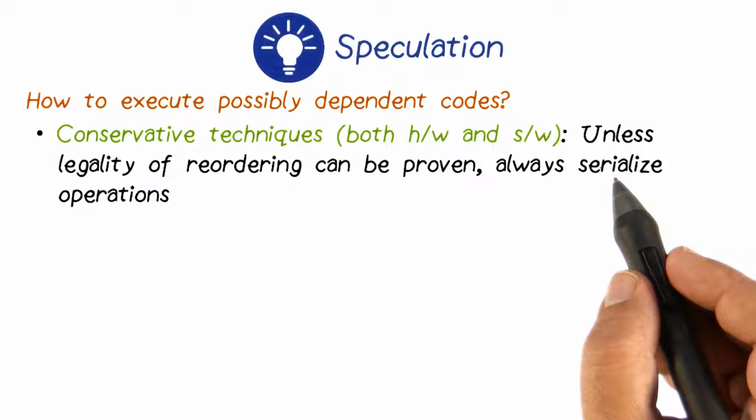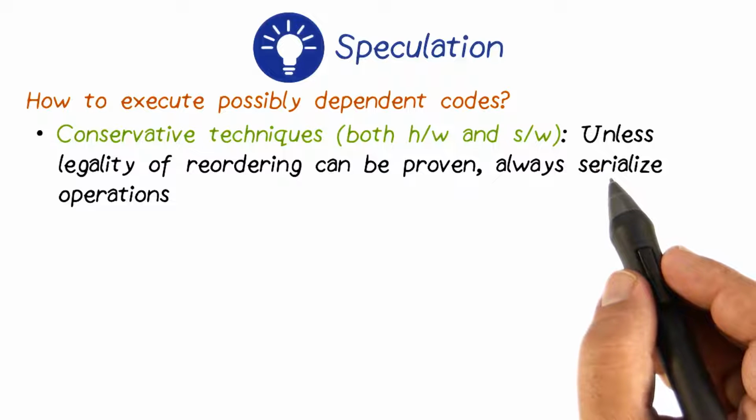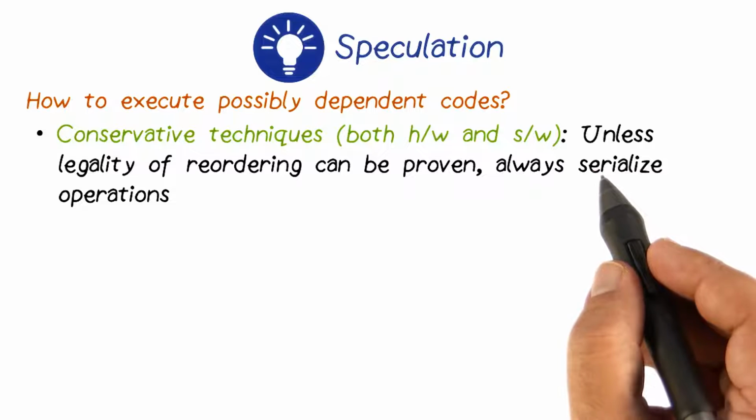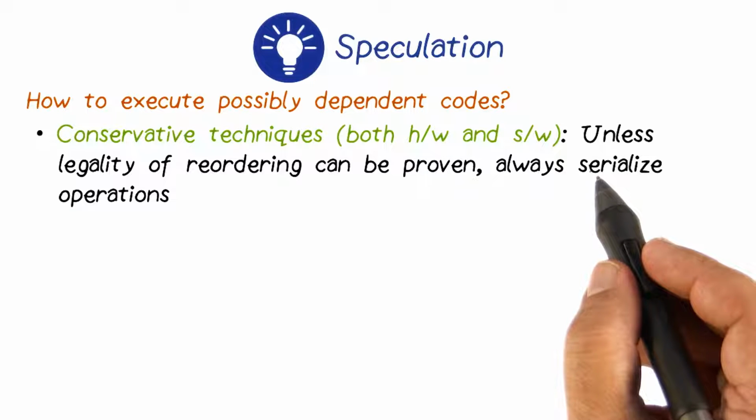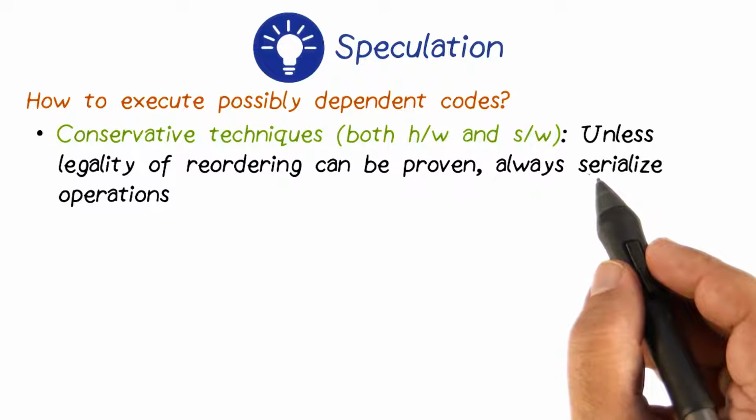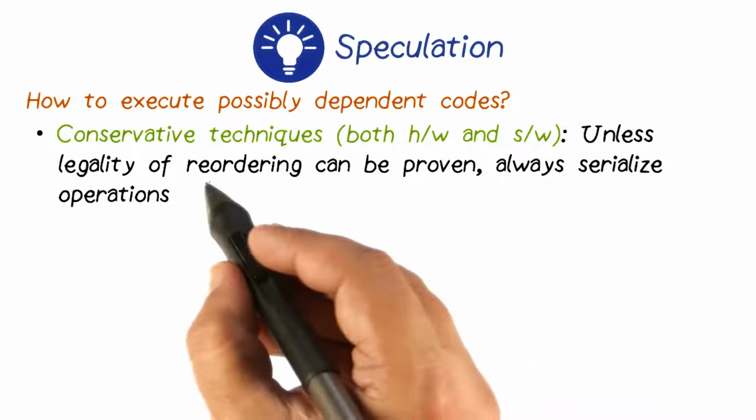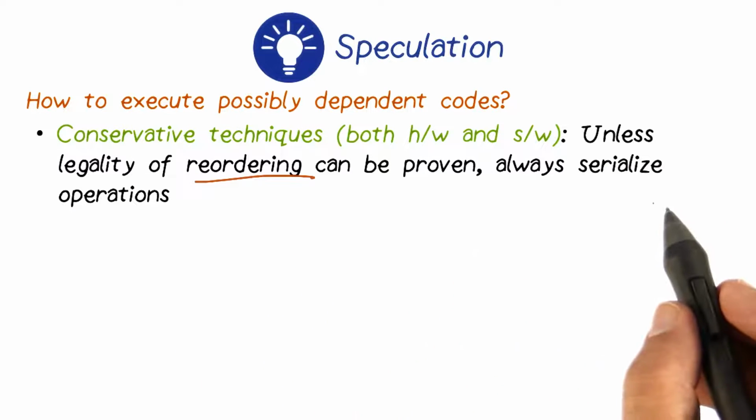In other words, imagine a load operation which is sitting on both sides of a branch. Now we can try moving it up all the way before the branch. We are able to move the load to an earlier place over the branch because, regardless of the outcome of the branch, we are going to execute the exact same load on either side of the branch, and therefore such a reordering is legal.